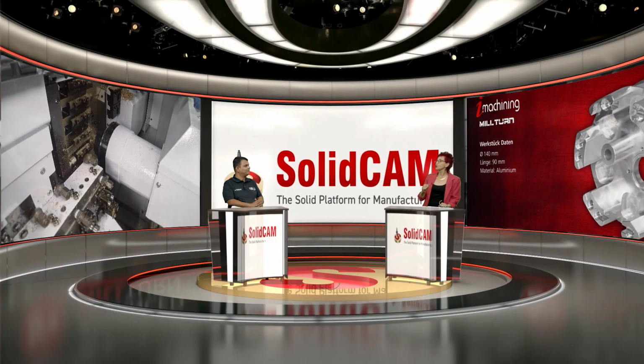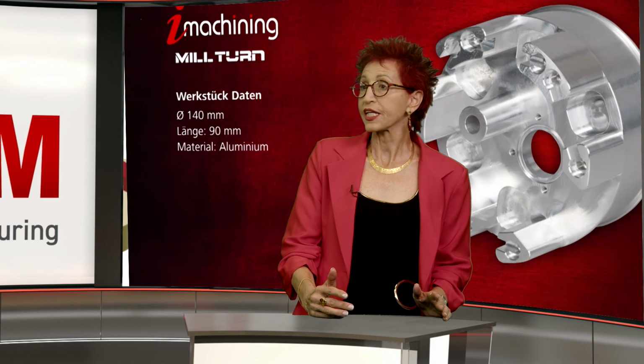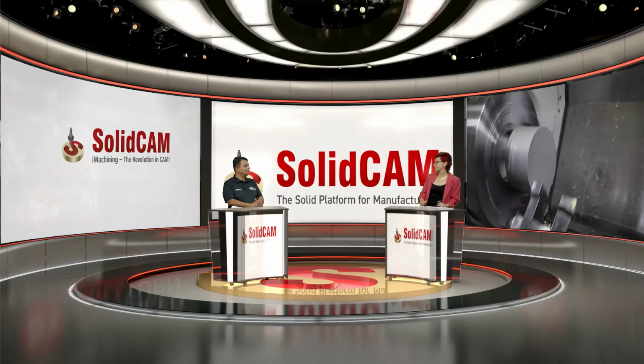Okay, and now the third question. What are the new things in simultaneous 5-axis that the users can look forward to in SolidCAM 2022? Sure. There are many features that we have introduced in SolidCAM 2022. Nowadays, barrel cutters are getting more and more popular due to their ability to take bigger step over and thus reduce the cycle time by almost 90%, as claimed by few cutting tool manufacturers.